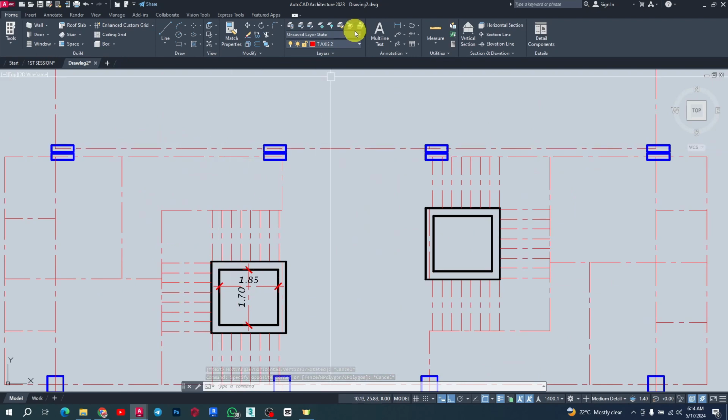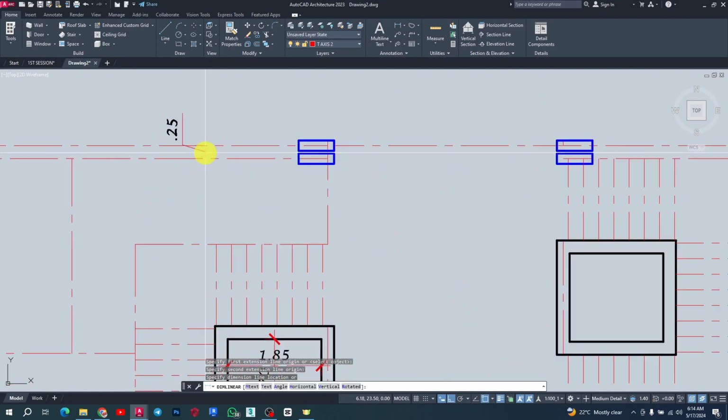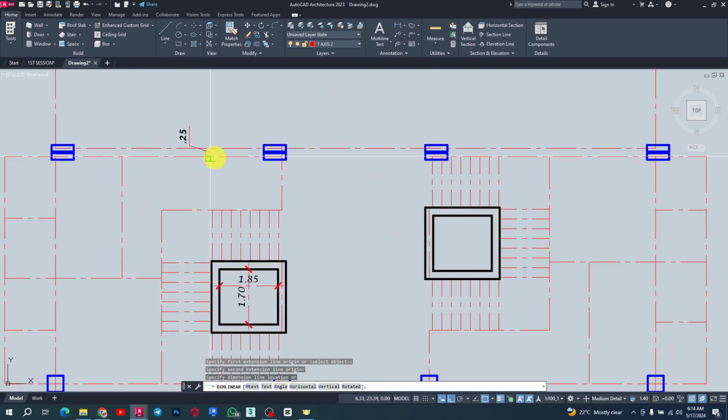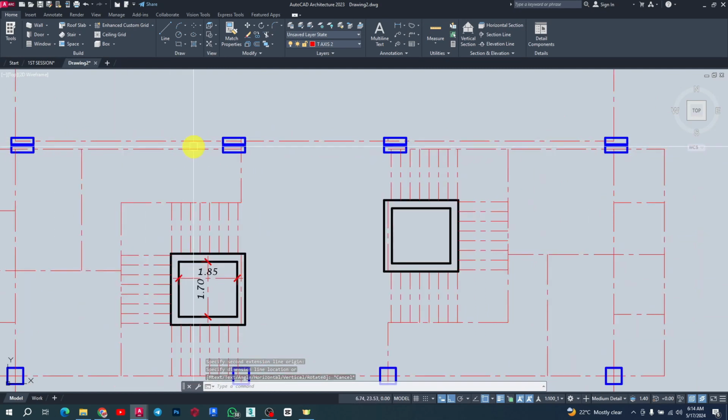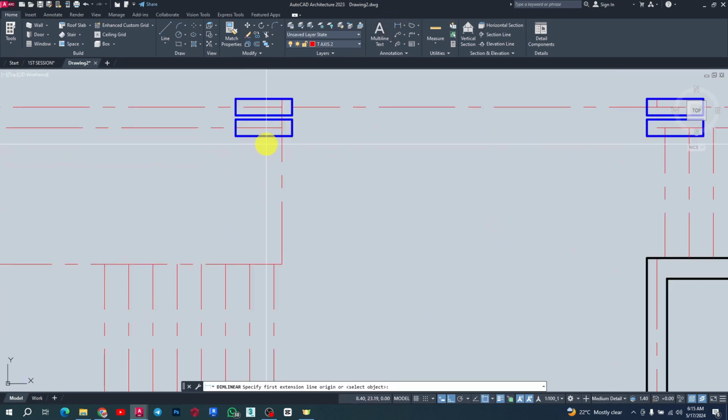So there's an expansion joint here. I'm going to be using a 5 millimeter polystyrene. If you want to use a beam here, because there will be a beam passing here, the polystyrene will pass in between the beam. It is going to separate the main structural elements, which are the columns and the beam, with the footing down there and the slab.